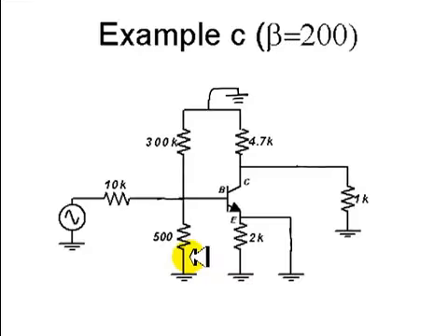But let's go back to the DC circuit, which is the one we need to solve today. We want to know if this transistor is in its linear mode, in saturation, or in cutoff mode. So let me bring back the capacitors, bring back the source on the top and the other capacitor. Not only that, in DC we know that those capacitors will be like open circuits.